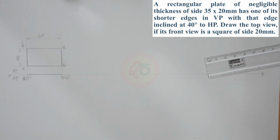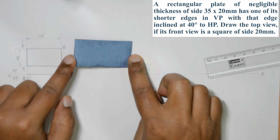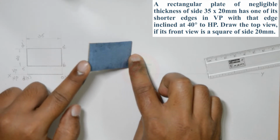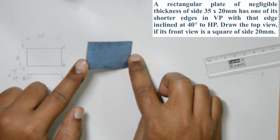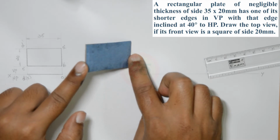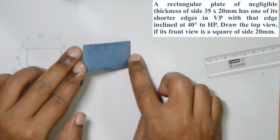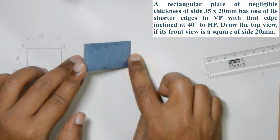So what he says is, this rectangle which is resting will get inclination until it is projected as a square. The longer edge will keep shortening by the lifting of the shorter edge opposite to the resting shorter edge, until the projection is seen as a square.